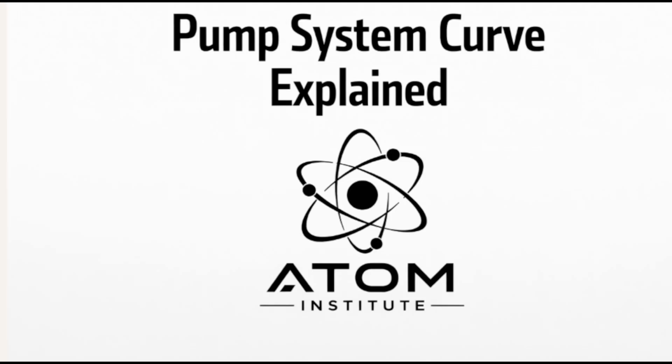In today's video, we are going to understand one of the most important concepts in pumping systems, the system curve. The system curve tells us how much head is required by a piping system at different flow rates. It is one of the key factors in selecting the right pump and determining its operating point. But before we draw or understand the system curve, we first need to understand the pumping system itself and the different types of heads acting in it.